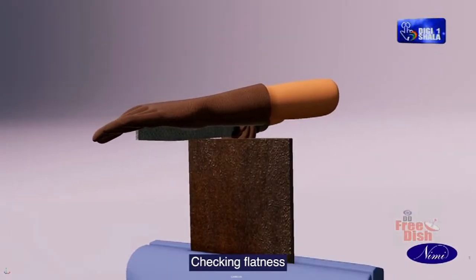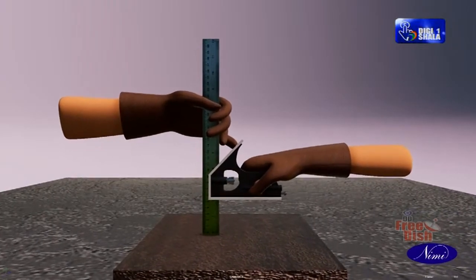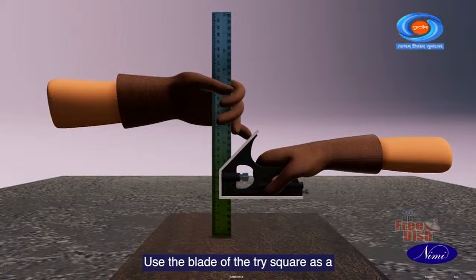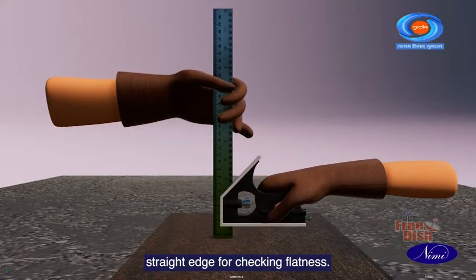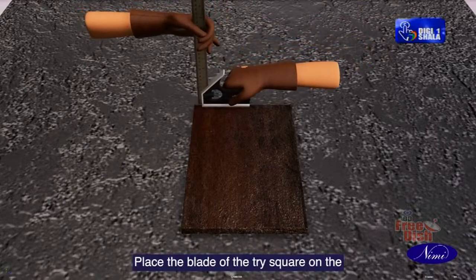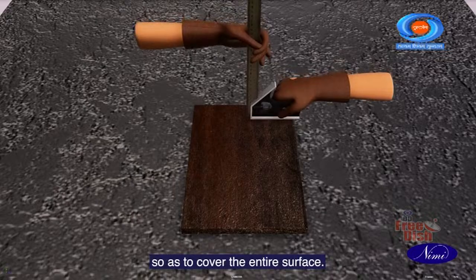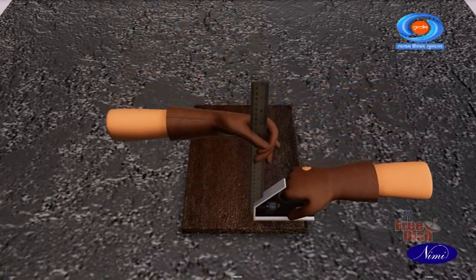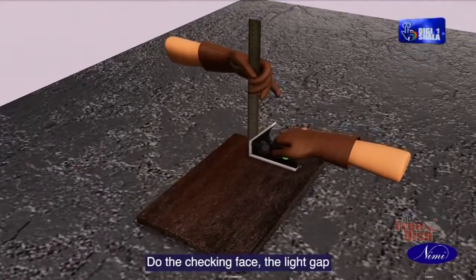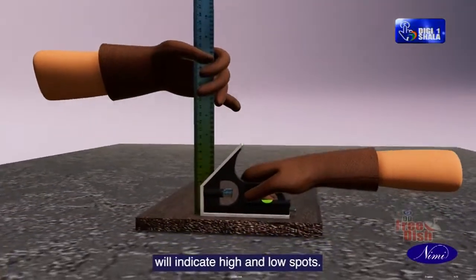Checking flatness. Use the blade of the tri-square as a straight edge for checking flatness. Place the blade of the tri-square on the surface to be checked in all directions so as to cover the entire surface. Do the checking. The light gap will indicate high and low spots.